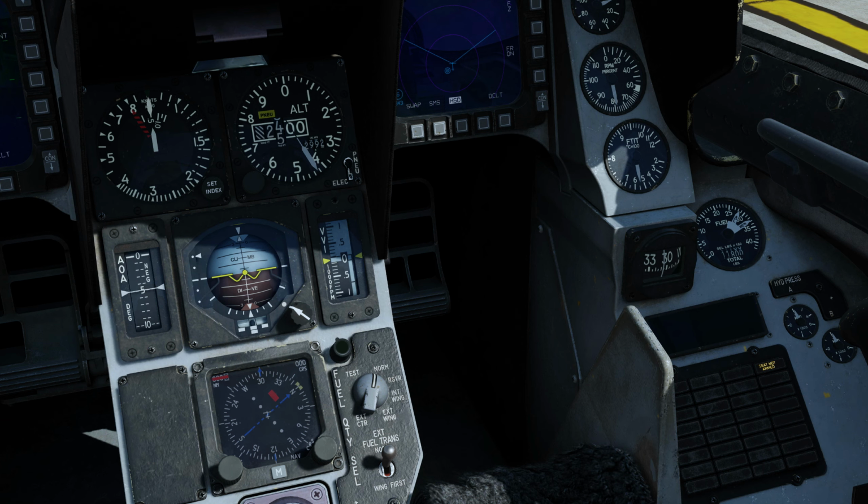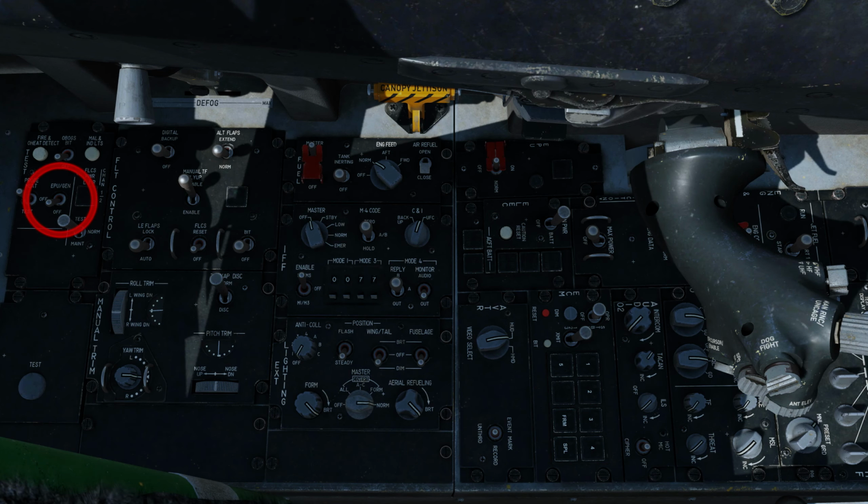With the aircraft on wheel chocks and toe brakes, increase throttle to 80%. Press and hold EPU/generator. Check the following lights: EPU air light on, EPU gen and EPU PMG lights off, 4 FLCS power lights on.